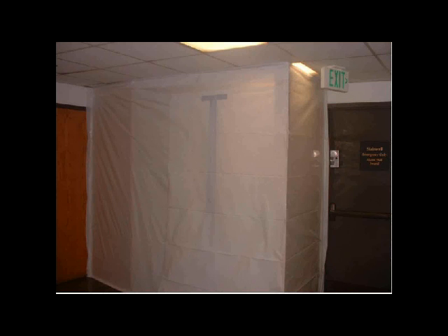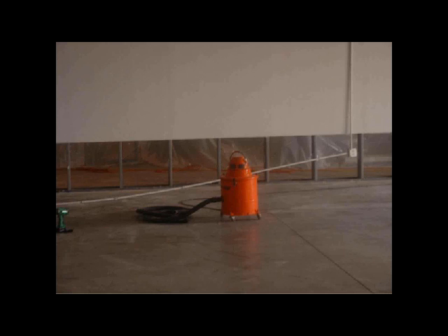Typical remedial setup: it's enclosed. There's an actual zipper door covered by another plastic, and remediation is commenced on the other side with air machines running. In a larger scale, where it was flooded, the flooded materials were removed and everything was cleaned up, still a little bit of dust there, but as you see the plastic behind, everything's been cleaned. This is an air scrubber that's run while remediations are done, or if there is just mold in the air, not present anywhere else, this is called air decontamination.